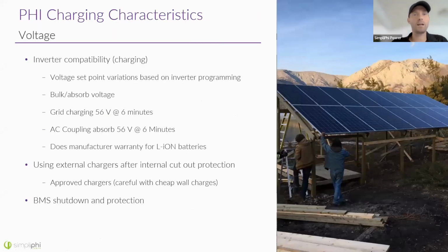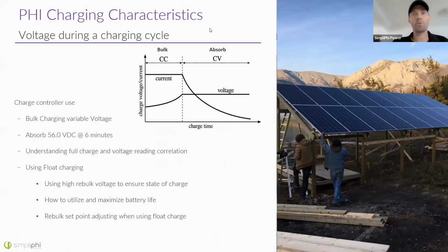So let's suppose we had 2 of those batteries, and we're going to run a charging cycle. So 2 times 37.5. So we would set our charge cycle to charge at 75 amps, and it will go at a constant current. But as it's charging up at a constant current, the voltage of that battery starts to go up. So at a 0% state of charge, we'd be at 48 volts. If we're at 50% state of charge, it'd be around 51.2 volts. That number depends slightly on temperature.